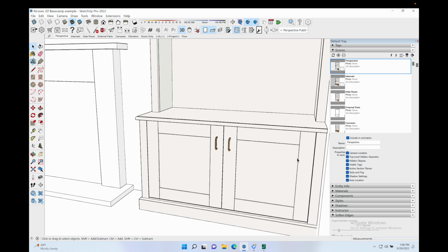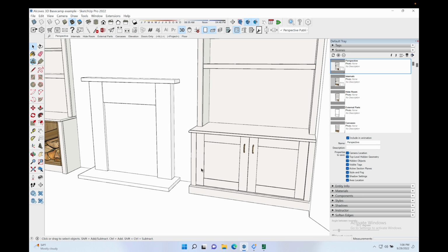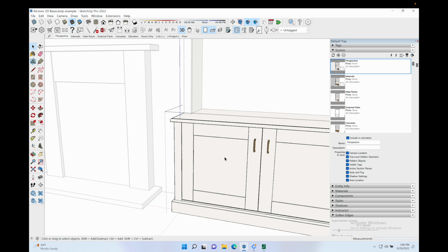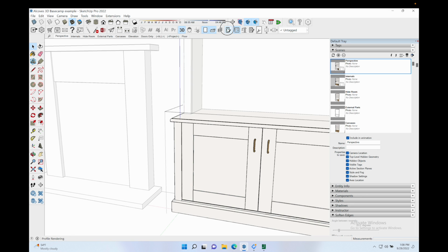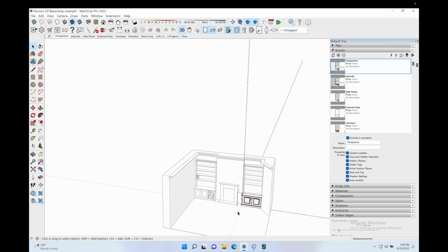And I have the option in CabinetSense of I can output all these 5 pieces. I can even tell that panel in there that I want it to have a certain overlap into a groove so that will come out on my cutting list oversize. Or I can render it as a solid door and machine this as one piece or two piece on my CNC machine, and that is how we do it.